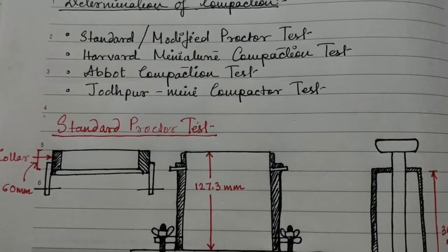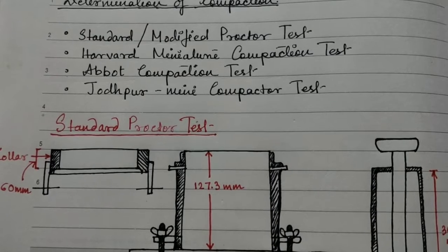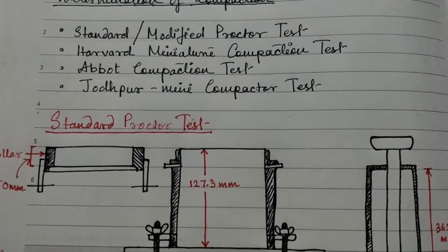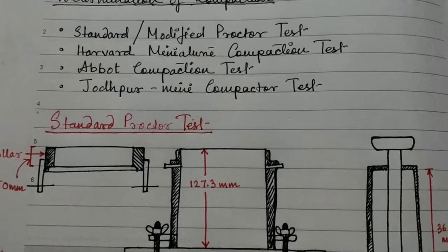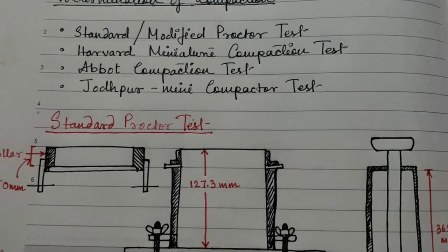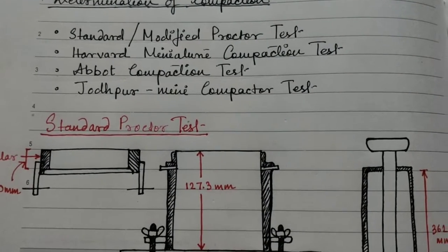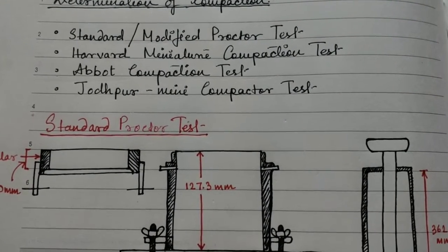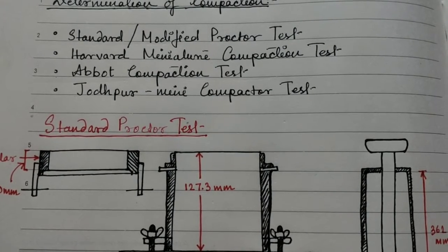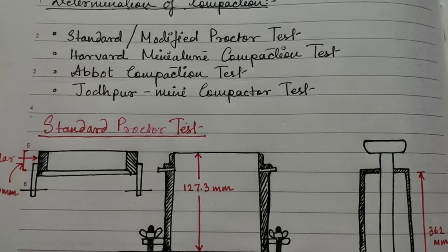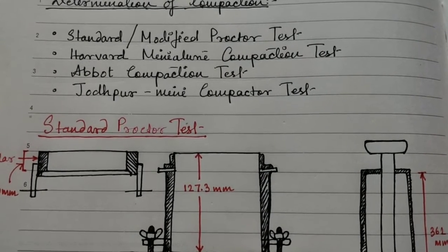As you have studied in the previous soil mechanics, the soil consists of three phases, that is solid, air and water. The main purpose of compaction is to release all the air present in the voids so that the soil particles can come into closer contact and in this way increase the density, or they can be compacted together so as to take more amount of load.